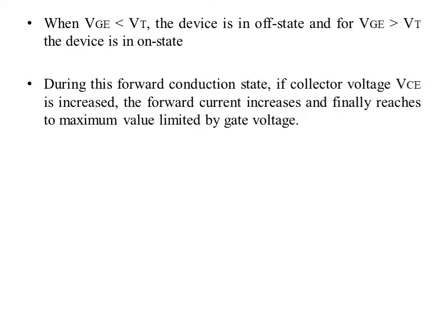During this forward conduction state, if the collector voltage VCE is increased, the forward current increases and finally reaches a maximum value limited by the gate voltage. Second, reverse characteristic.